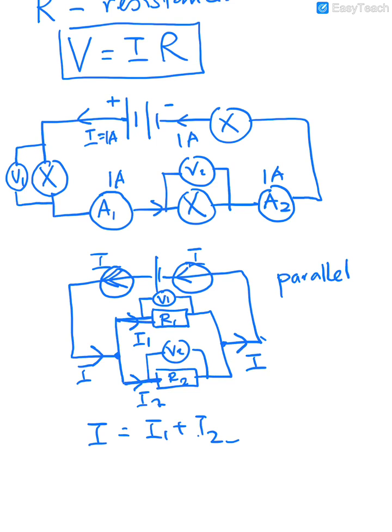Why not? Two reasons. A voltmeter is designed to measure voltage, not current, so it doesn't take any current to it. And the other reason is that it has a very, very, very high resistance. So no current will go there, but everything will go through this light bulb here and proceed. It doesn't split again to the voltmeter, but goes round and back. So this still remains a series circuit.